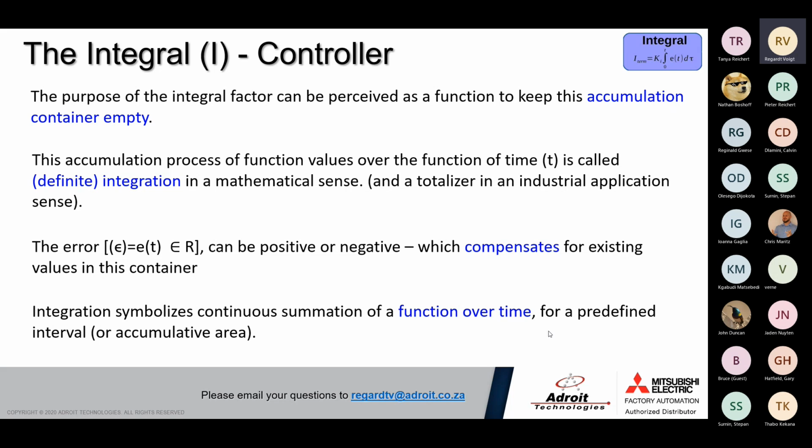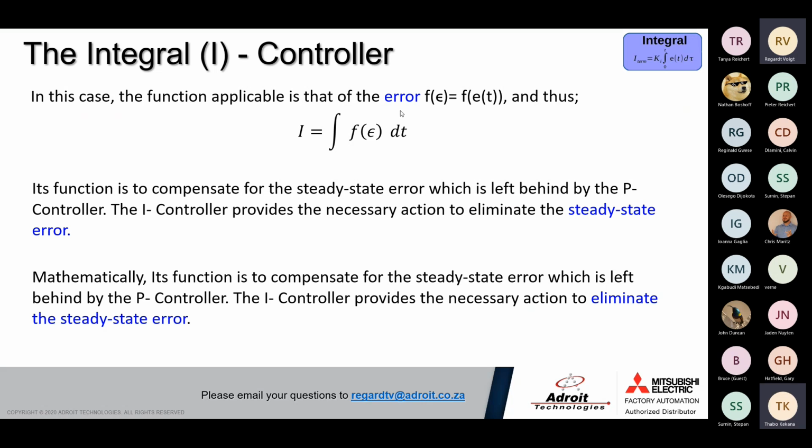Okay, so we discussed this part here. We said it's a function of the time. Yeah, that's perfect. So there's the mathematical formula for the I controller. As I mentioned, it uses the integration of a function. In this case, the function is the error. So it would accumulate all of the errors over a set of time, and will control the VFD or valve or heater or whatever actuator is in that regard.